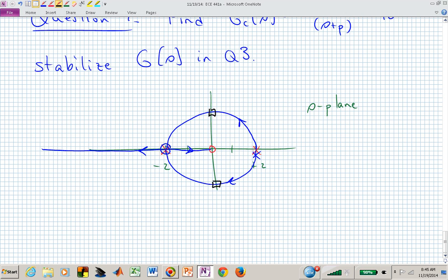And if I was on an exam and I had to calculate a stabilizing controller very quick, I would say, oh, let me just pick one there, and maybe my second pole was right there. My third pole is actually right there. It's stuck because I canceled that pole. I still have 3 poles in my system, closed loop, and that one's stuck right there.